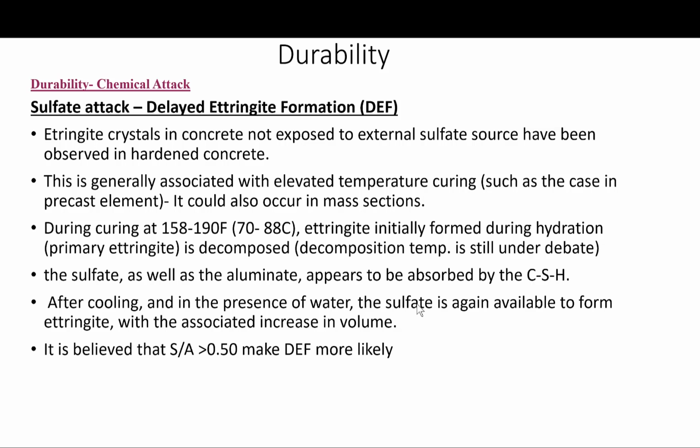So this procedure has several drawbacks. The major objection is that the test is too slow for use as a routine specification test, and the behavior of concrete does not necessarily parallel the behavior of the mortar bars done in the lab. Also, realistic exposure conditions are not reproduced. Again, the test is only for use with Portland cement and does not assess the behavior of blended cements, or cements blended with pozzolans or slags.